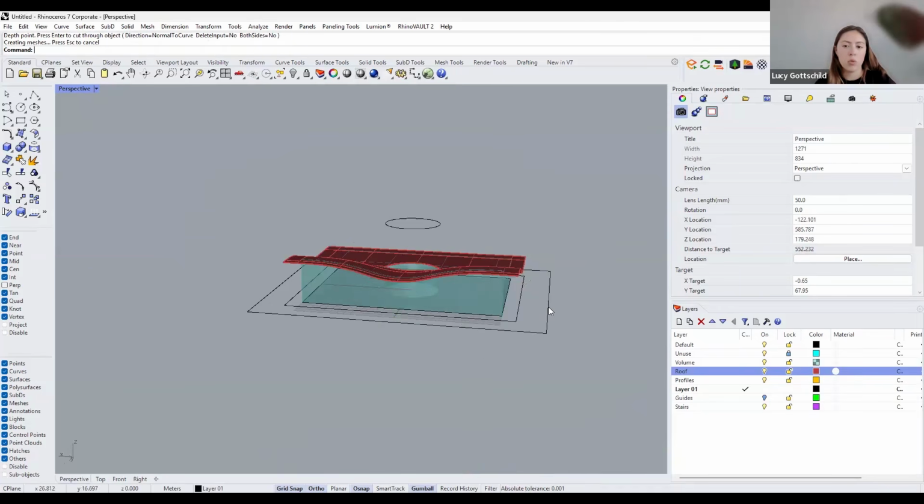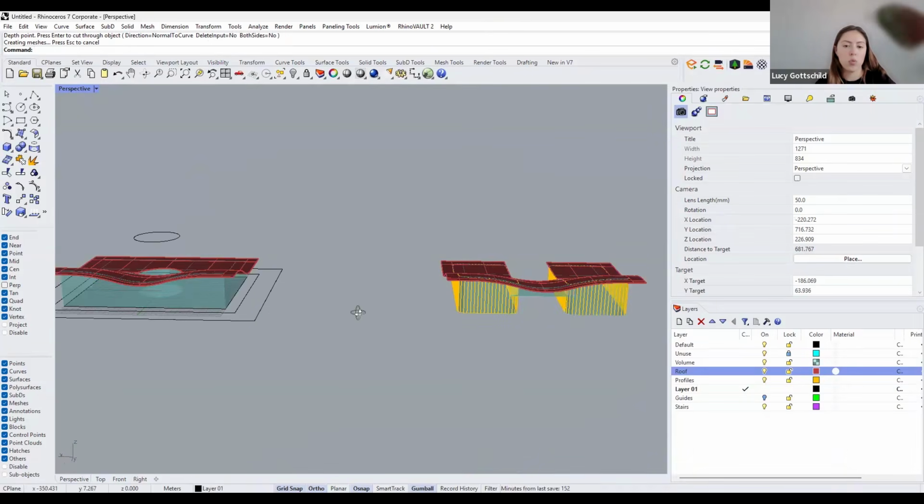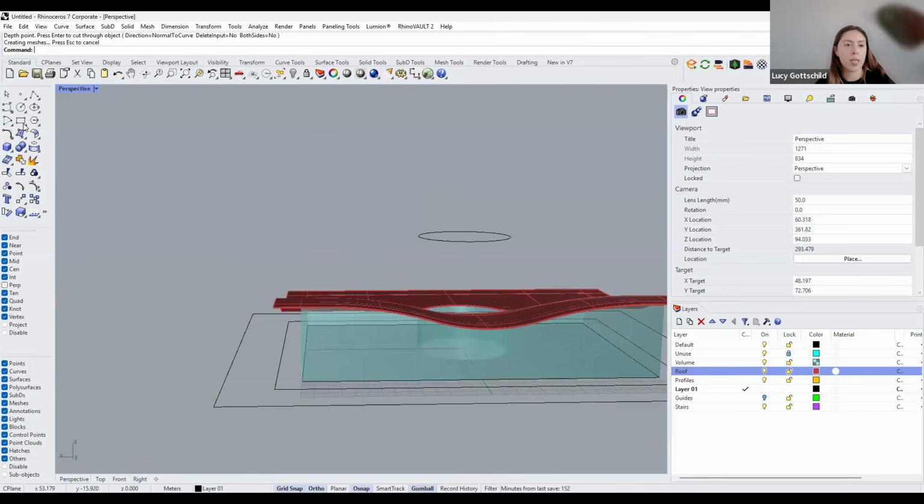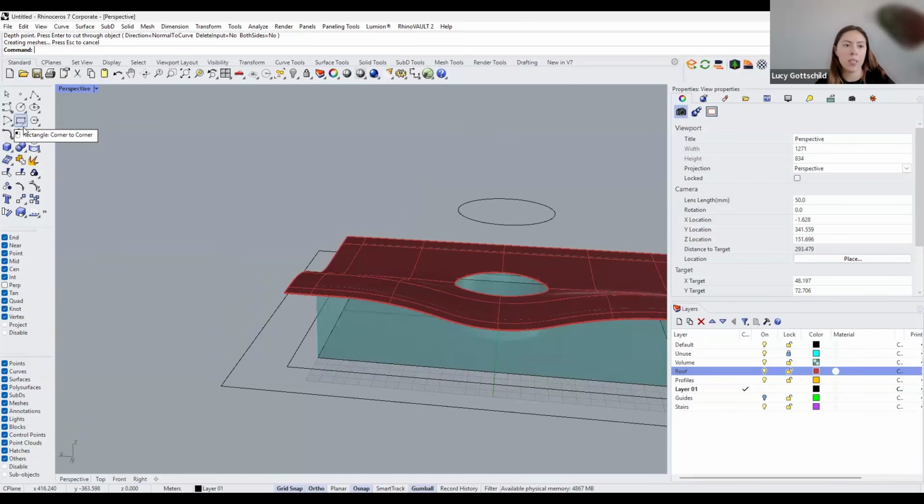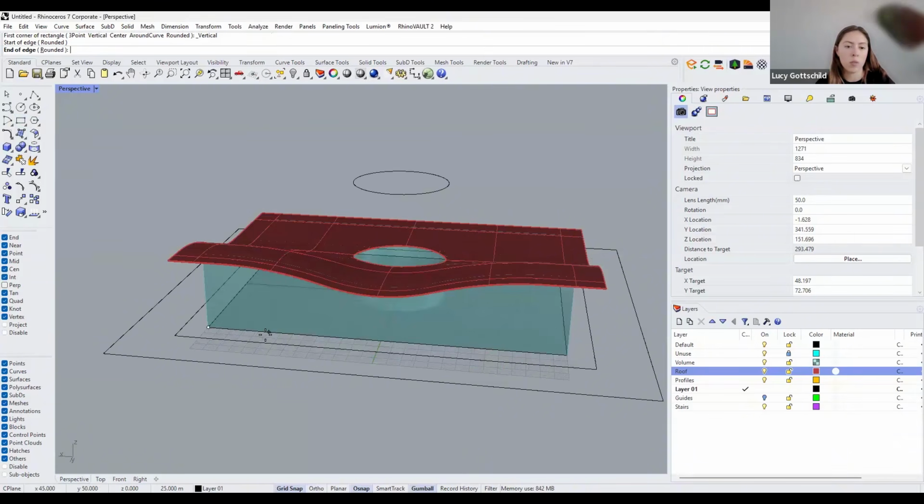Now we want to continue doing this abstraction. So what we can do is just on the rectangle menu or in this command, you have this cascade of rectangles. So you click on that, and then you go here on the rectangle vertical. And with this, you will click first in one of the corners of our model.